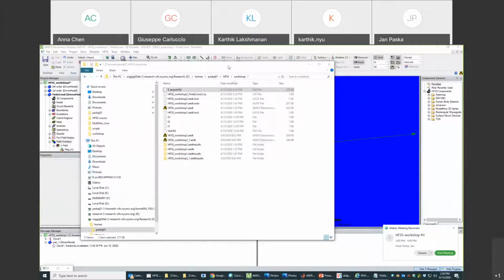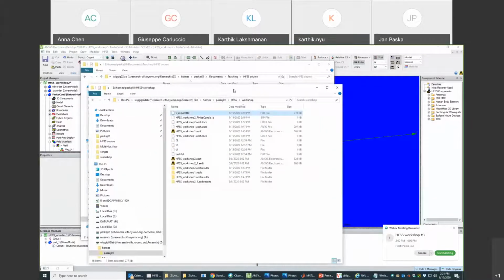The export, especially when you have many points, can take a long time compared to, let's say, CST. The reason for that is the inherent mesh structure. In CST, you have an orthogonal grid, and you can export very quickly on those grid points.